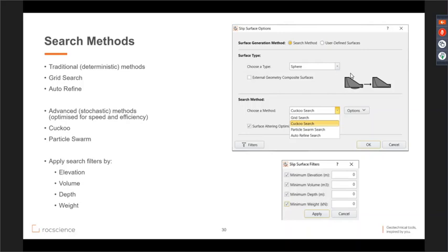Within Slide3, as I showed in the example, you can either define weak structures as ubiquitous joints, or define a combination of ubiquitous joints in an anisotropic material model with user-defined weak layers. They also have a specific wedge search function here.